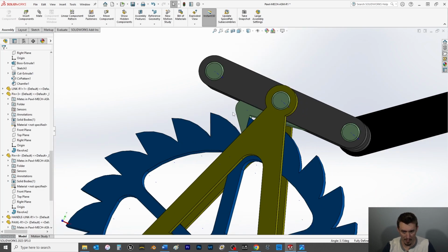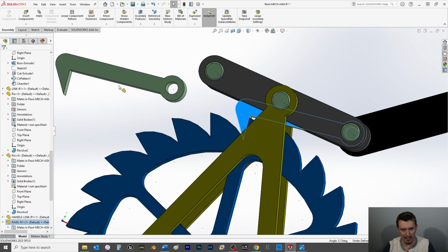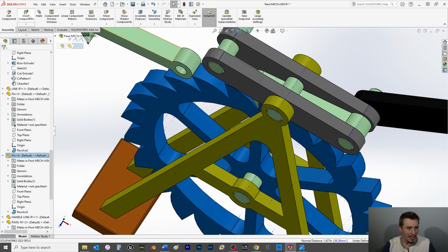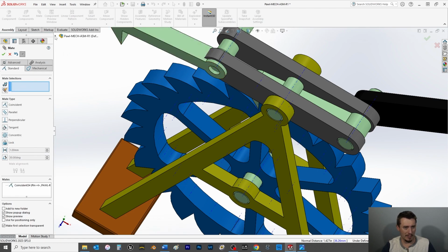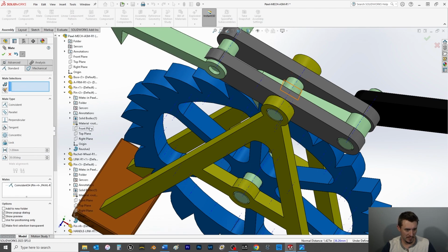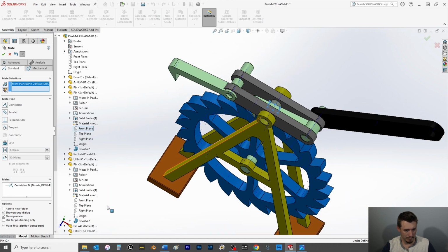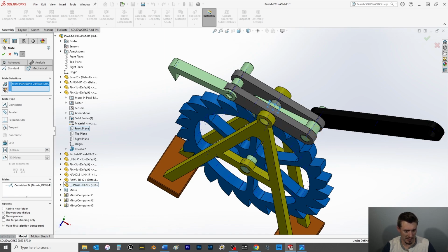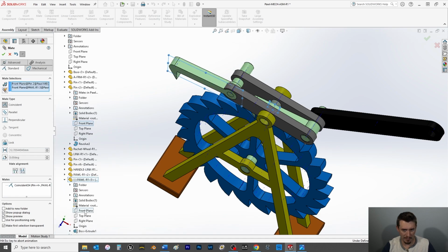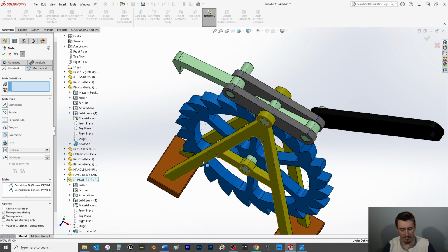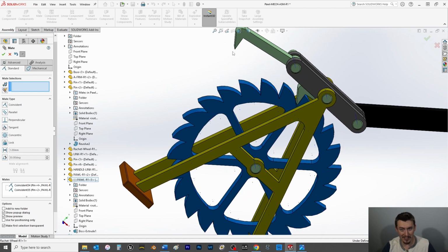And I'm going to press the Control key on the keyboard, drag that part out again, make this axis, mate it with the 4th pin, and then I want to take pin 2 again. It's front plane. And this time I'm going to collapse pin 3, collapse R1, and we want the front plane there, so that's centered. And let's see if this actually jives. Should come down.